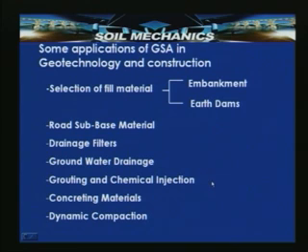And road sub base material, as we said, to provide a mechanically stable foundation, we are required to have good knowledge about the grain size analysis of the particular material under consideration. And for drainage filters, basically it is required to know the drainage characteristics of the filter material with the adjacent soil characteristics. And groundwater drainage, and grouting and chemical injection. This is a phenomenon to strengthen the ground or to fill the voids or cavities in the ground. Grouting is a phenomenon in which a chemical injection or cement sand grouts are inserted into the ground.